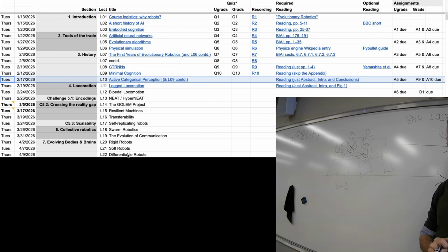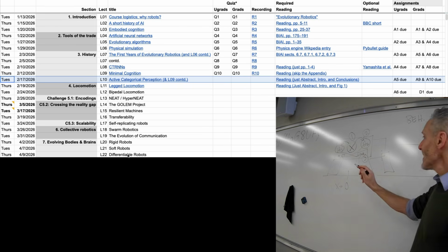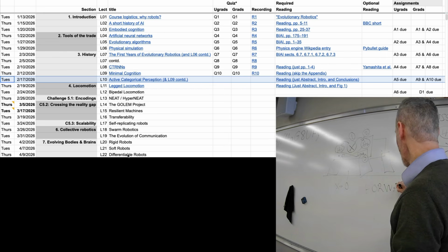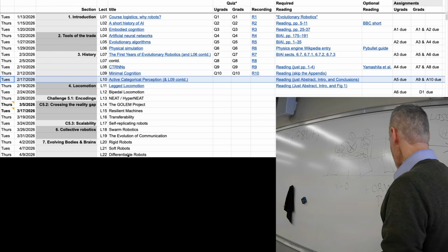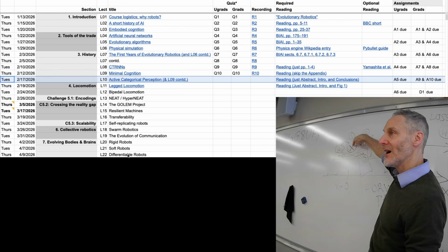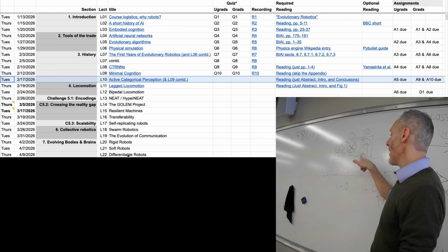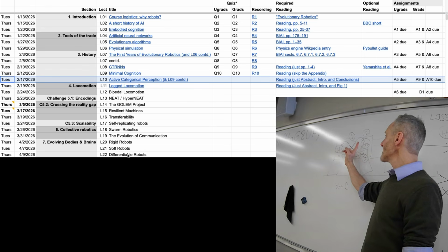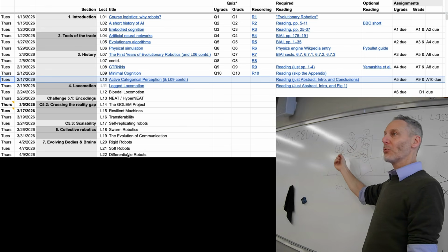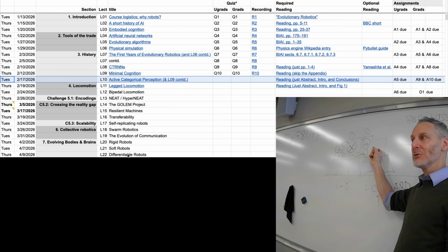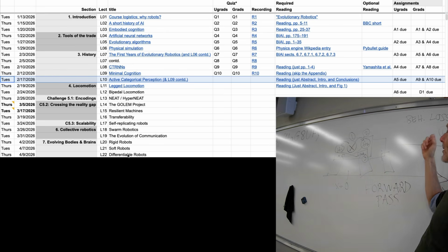How bad did the robot do at whatever we want it to do? And in the differentiable simulator, we have now completed what's known in machine learning as the forward pass. The forward usually refers to forward from the input layer of our neural network through to the hidden layer and out to the output layer in traditional neural networks. Similar here, we're also moving forward from the input neurons to the hidden neurons to the output neurons, but we're continuing the forward pass into the physics of the robot, into F equals ma, and into computing behavioral loss.